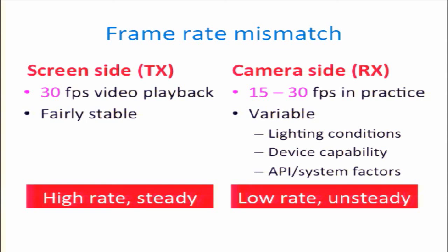But the reason there's a range of frame rates is also because you have different lighting conditions. If you want your image quality to be good enough, you need to get enough light to get something sensible. That's also a reason why sometimes you don't want to run at a very high frame rate anyway. For example, if you fix something in the firmware, you can always say, whatever happens, as long as the hardware doesn't burn, you can always give me an image at a fixed frame rate. But that may not be anything useful, right? So that's the lighting issue in that case.